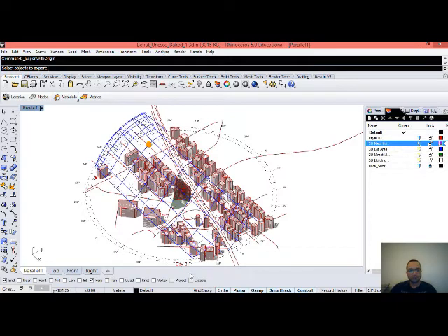For sure, you have to select the objects of your model, and these should be 3D objects. So in this format, only 3D elements, solids, will be imported. Single lines are not going to be recognized by the exporting format.